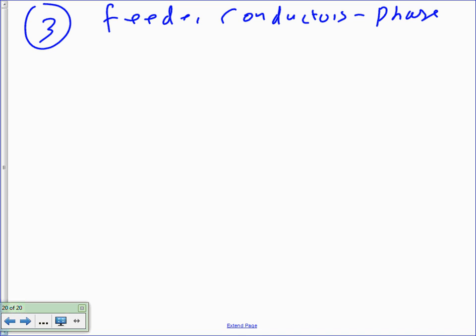Now here's what I want you guys to do. 240.4(B) would tell you. First of all, give me the amps. What can you guys give me as the amps of the load? The load amps. Was it 267 amps? If you go to 240.4(B), it allows you to size the conductor based on the load. You can grab the 267 and size the conductor based on the load. Cool? It allows you. Now remember, we're engineers. It's not a good idea to do that, even though the code allows you to do it. Am I clear about this?